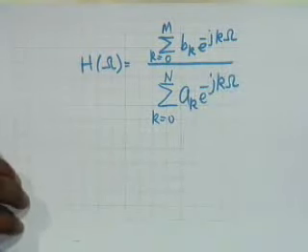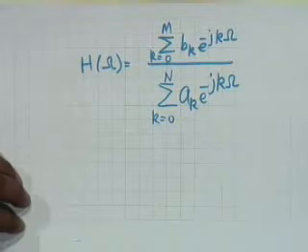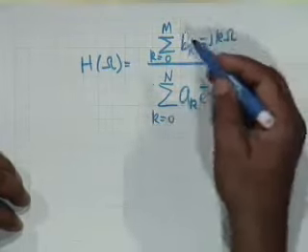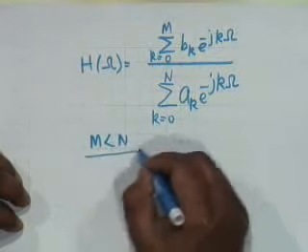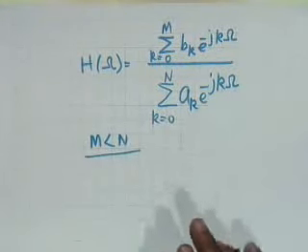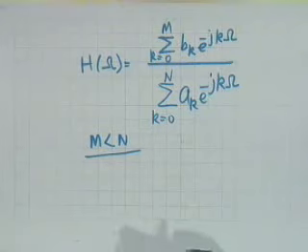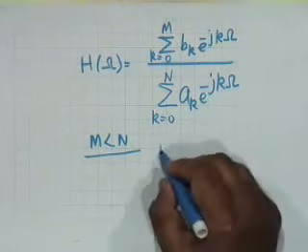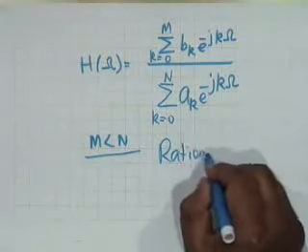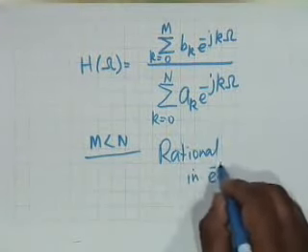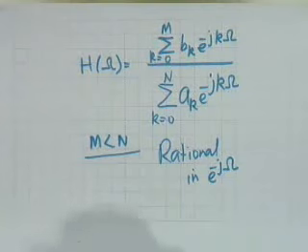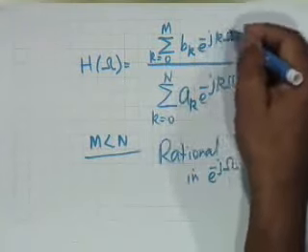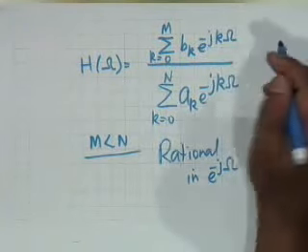This is the frequency response function in the most general case, and you notice that if M is less than N, alright, the first thing you notice is it is a rational function, is it? In what? What is the variable? That is right. It is rational. You must define your variable. It is rational in e to the minus j omega. It is not rational in omega. Obviously it is irrational because there is an exponential power involved.